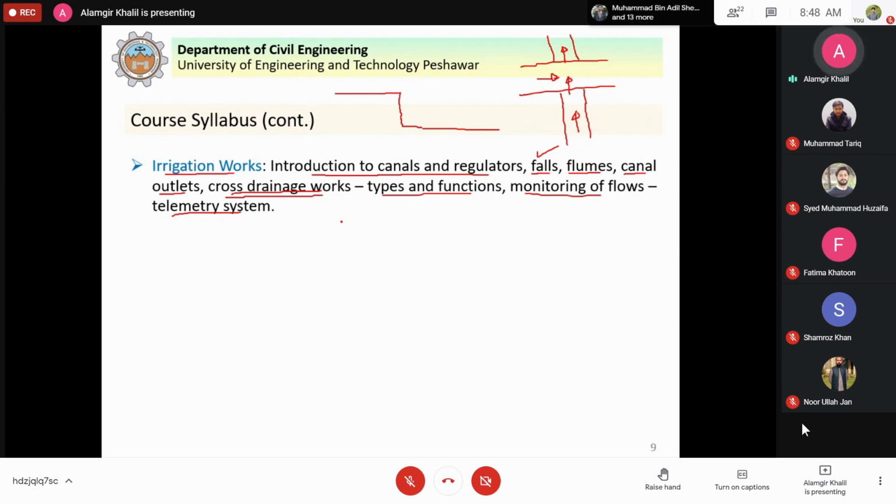So if the depth is shallow, we calculate the average velocity at 0.6 times the depth of water, or the 2-point method where you use 0.2 and 0.8 times the depth of water and then average. So you can develop the rating curve, which is the discharge versus the depth.